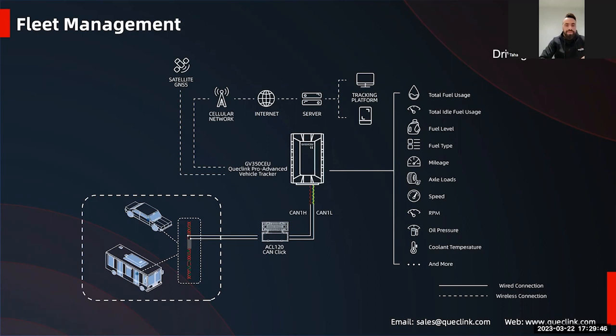So when I'm talking about fleet management, we are talking mostly about a device that can get fuel level, fuel consumption, also the idling time, the speed. These are most of the parameters, and you can extend your parameters as much as you can. So in order to get the right parameters, this is maybe certainly for our technicians. The first thing, you have your fleet, you have in the GB350CU pin 19 and pin 20, which are dedicated for CAN1, the CANbus standardized system or protocol.